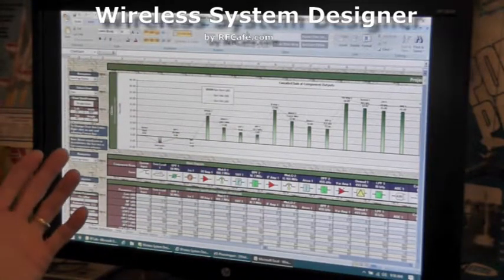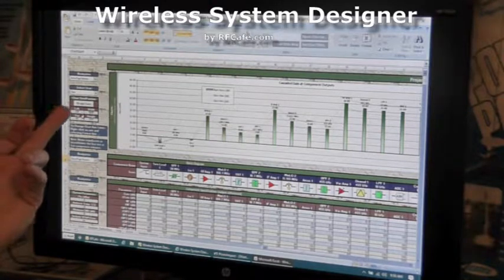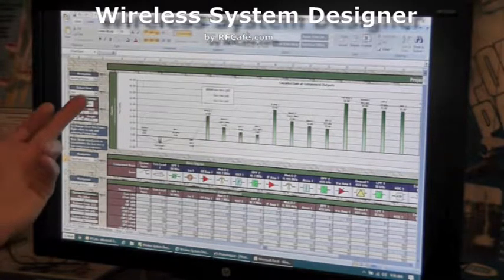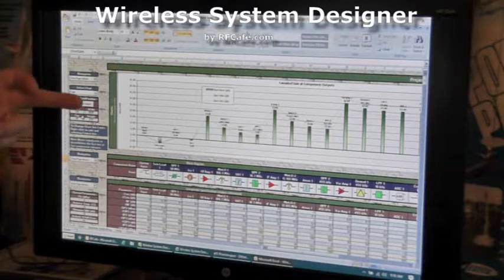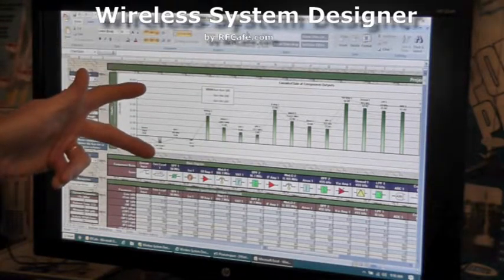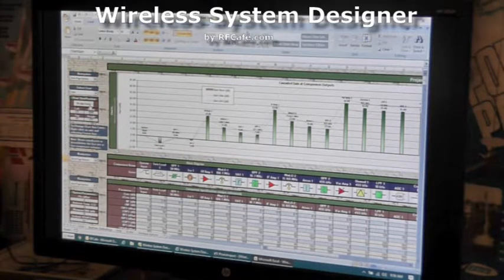However, to make that easier, I provided a place to define where the left top corner is, and then how wide and how tall the charts are. And if you press this Align Charts button, I'll go ahead and do it, it's not going to change anything. It goes through and sets all, right now there's 20 of them, it sets all 20 of them to the same settings so that everything's nice and neat.